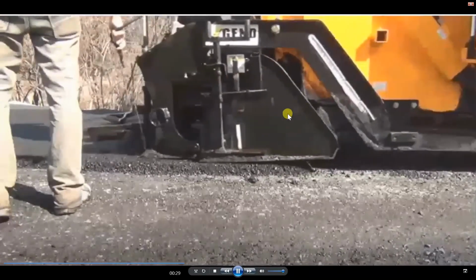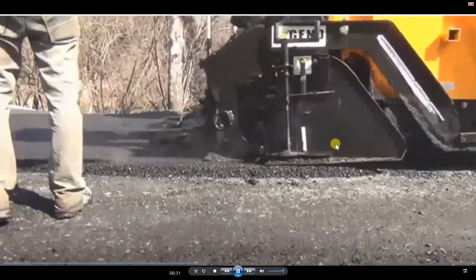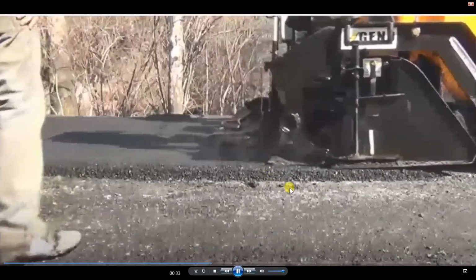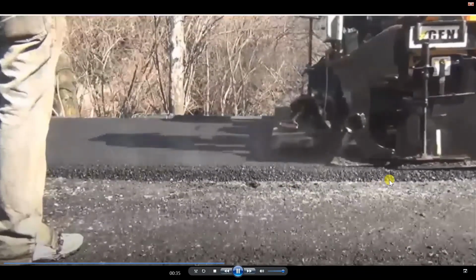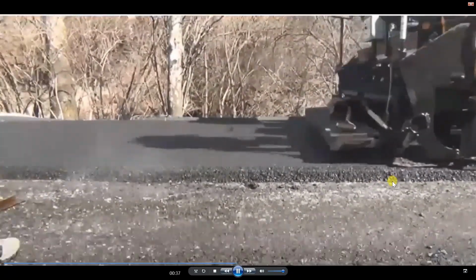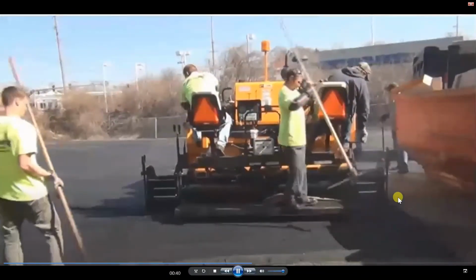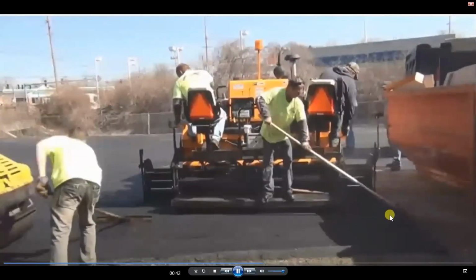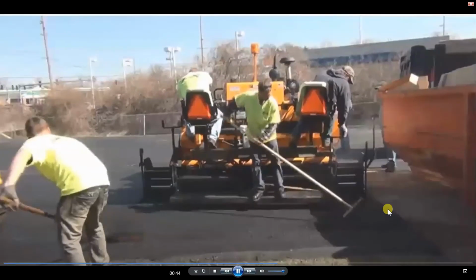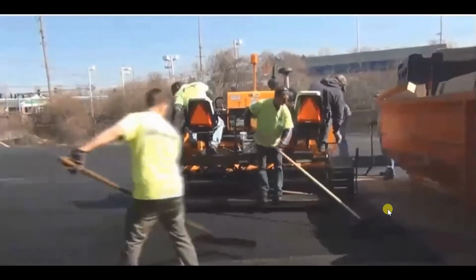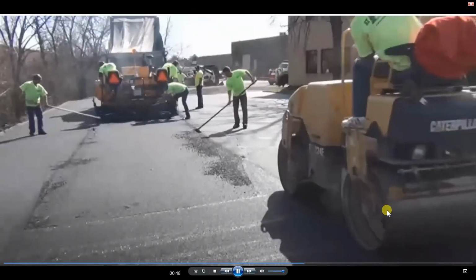The operator uses his controls to adjust the width of each pass and to direct the flow of asphalt around obstacles. An overlay, at its most basic level, is a series of paver passes, which are 9 to 15 feet wide. The area where two paver passes meet is called a seam or a joint. It is critical that these joints stay as hot as possible so that the mix on each side of the joint can be fused together.